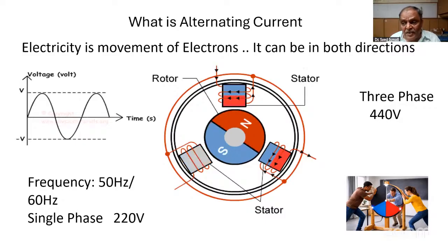But the problem when you design with 3-phase is that if one phase comes off, if it's absent, your motor winding will get damaged and will not work properly. So you have to have all 3 phases. 3-phase electricity throughout Asia is also much cheaper than getting single phase, because generation happens like this with 3 coils at the generating place and is then transmitted. So that is why we always try to use 3-phase.